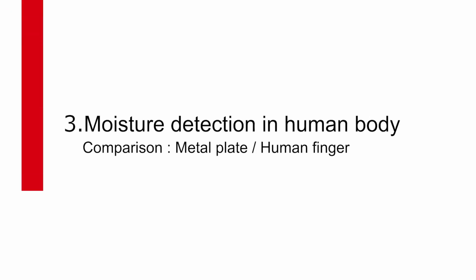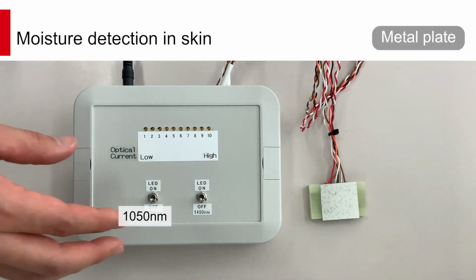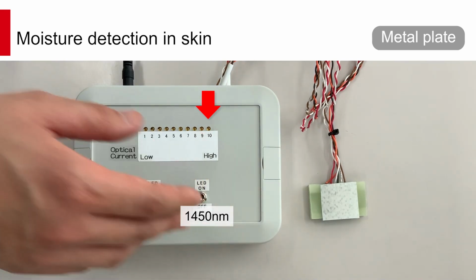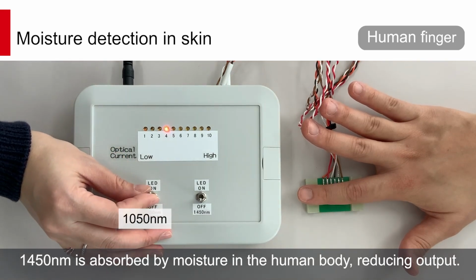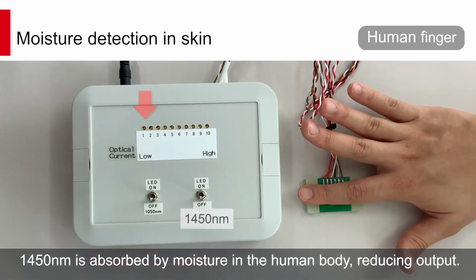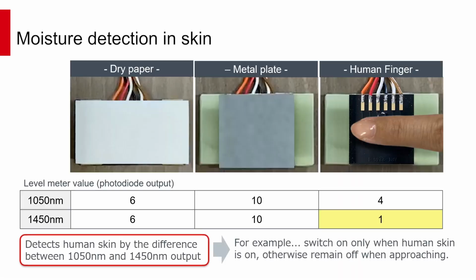Now let's try it with a metal plate and human fingers. The metal plate does not absorb light and both values are high. The other side, in the case of a human finger, the light is absorbed by the moisture contained in the skin, especially at 1450 nanometers, and the value is low. By detecting the moisture contained in human skin through output difference, it can be applied, for example, to a system that switches on only when a person approaches.